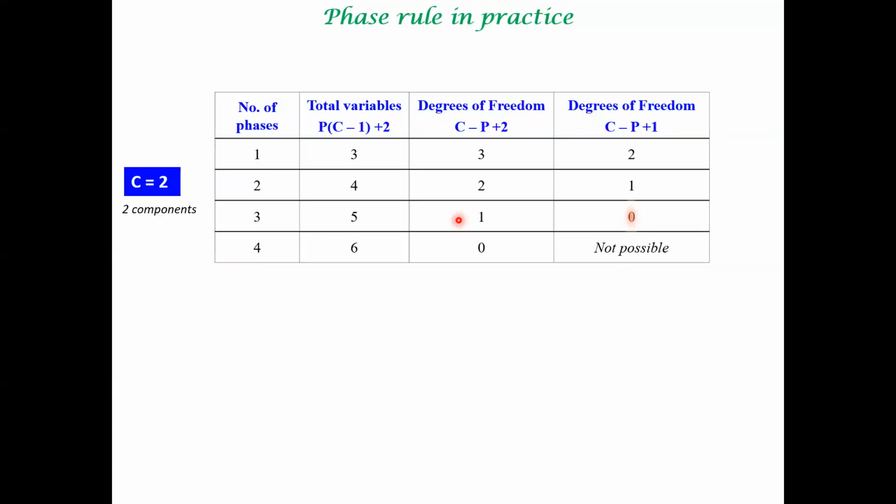All right. So if you have a 2-component system, let's say you're looking at a binary phase diagram. If you have a single phase region, the degrees of freedom is 2. If you have, let's say, 3-phase coexistence, okay, 3 phases in equilibrium with each other, then implementing the formula, you would see that the degrees of freedom is 0. That means you really do not have a choice on any free variable.